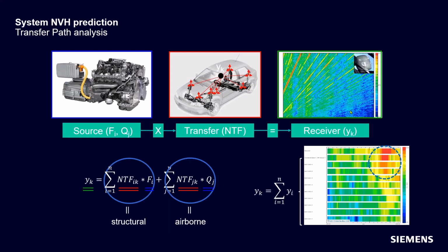And this receiver is typically a microphone or an accelerometer, some place where usually an operator is going to experience either the noise or the vibration or both of this device. And so our sources are typically engines or motors or airborne noise sources, that kind of thing. Paths, or the transfer paths, are typically either structure-borne paths through the physical structure, so where the source mounts to the device. If they're airborne paths, it's literally the air path between the surface of the source to our microphone location in the driver's compartment or wherever our receiver might be.